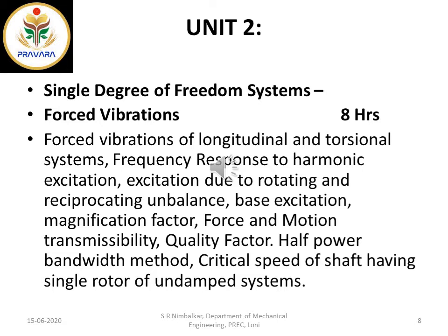And transmissibility is one more thing. When you are restricting, absorbing or isolating the vibrations, transmissibility is one factor that helps you determine how much force or how much vibration you can isolate or absorb, isn't it? So that is force transmissibility and motion transmissibility. We'll study that along with the quality factor. Then there is the half power bandwidth method to analyze this force transmission.